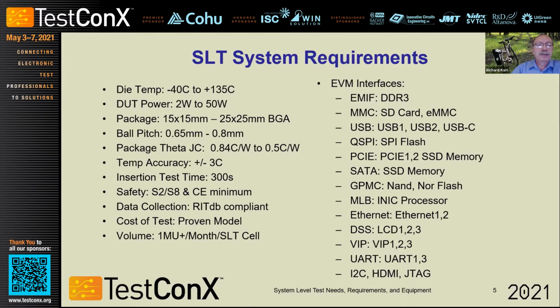On the right, we wanted the vendor of the SLT equipment to supply the EVM controller. So listed on the right are the different EVM interfaces. We were able to significantly reduce the controller interface need in the end to only those needed to start and stop testing, communicate results, and reprogram the EVM firmware as the test procedures change, right? So those are our requirements.